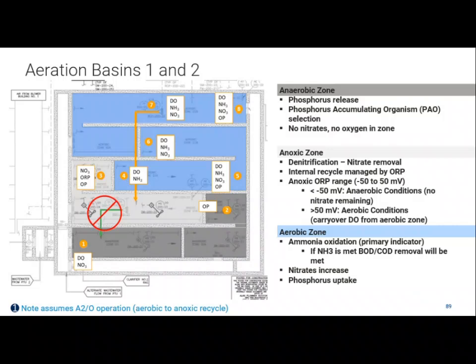Enough PHA? It could be PHA. Keep going. What is it? The BOD, right? There's got to be enough BOD to do denitrification. If you have nitrate leaving your anoxic zone, it means you had more nitrate than BOD.